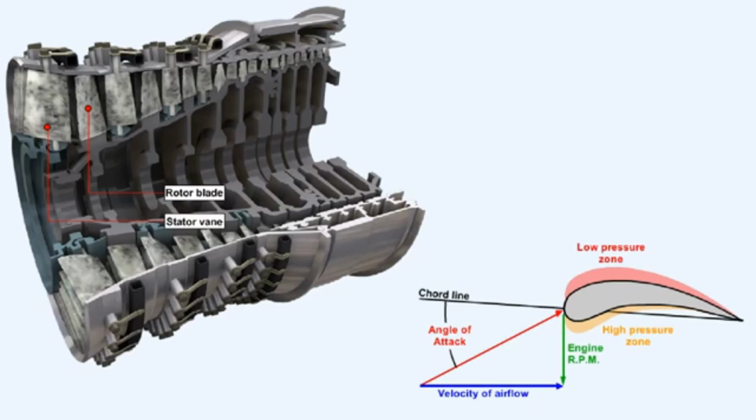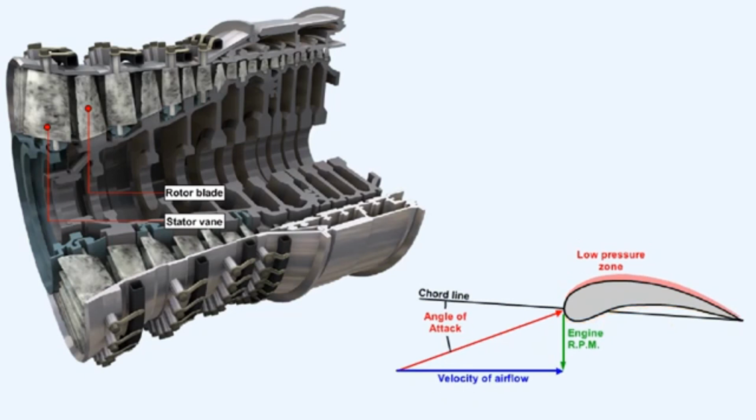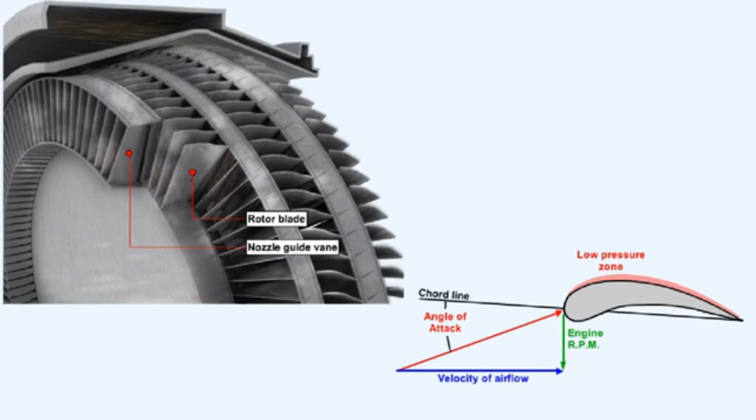Contaminated or damaged compressor components, rotor blades or stator vanes, which will reduce the efficiency of the compressor as a whole. This will cause an increase in the axial velocity of the airflow through the compressor because of the decreased compression ratio. A contaminated or damaged turbine will not be capable of generating the power required to drive the compressor at the correct speed. This will make the compressor incapable of generating a sufficiently high compression ratio, which in turn will mean that the axial velocity through the compressor will increase.